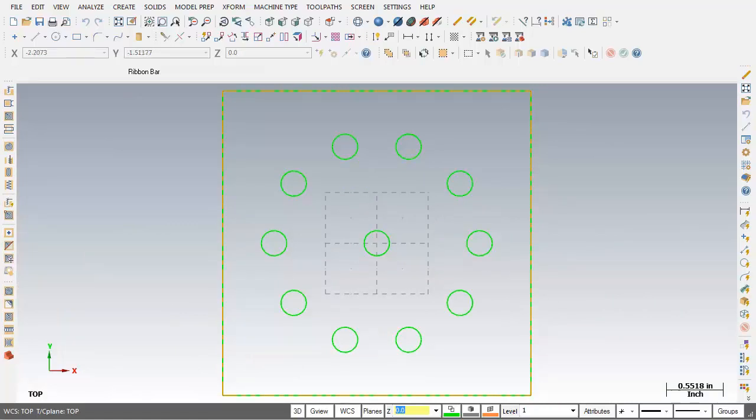I'm going to go ahead now and delete some entities. So I'm going to move up to the top of the screen, click on delete entities. Now on the general selection ribbon bar, if I open up this drop down, we've got a series of options: in plus, out plus and intersect. Let me leave it on in, and what I'm going to do is draw a window around a series of entities. So I've picked a point,